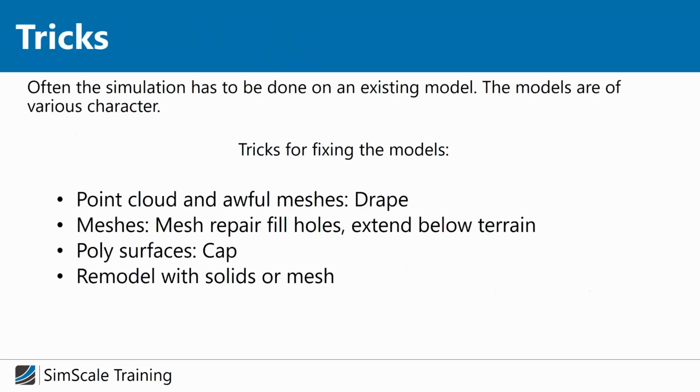So as I mentioned last time, when you're doing wind CFD, then you have model demands that are much different from doing architectural presentations. You need to have solid models, and often when you get a model from the architects, they are not of the quality you need for doing CFD.